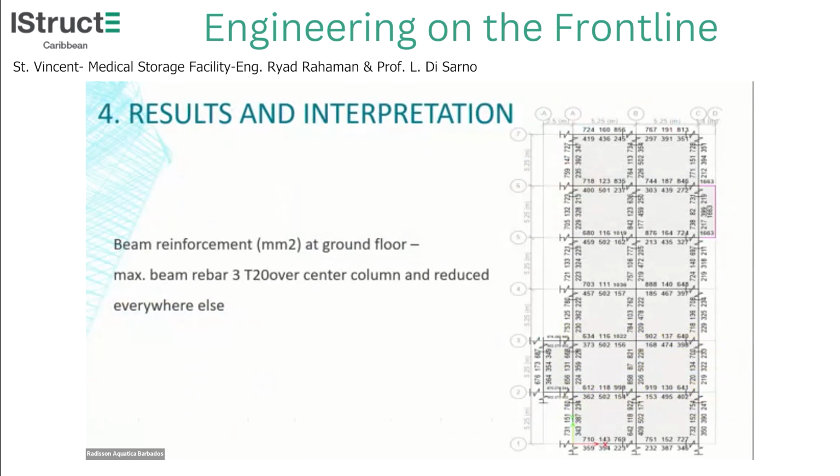So let's see what the reinforcement design looks like. This is ground floor. Let's go to the junction in the middle, which should have the highest moment. You have 1,022 millimeters squared for your 450 deep beam. Not bad. Everywhere else, 750 something, 703. This is ground floor. Looking reasonable. Reduced carbon footprint, less material. Next slide.